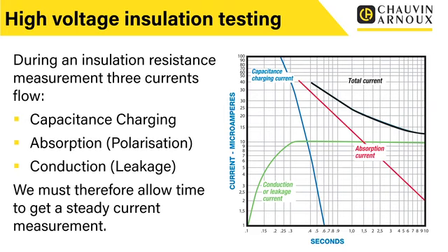Obviously using a DC test voltage, there will be a positive and a negative. Within that insulation, there will generally be a random alignment of all of these molecules within the equipment. When we actually place the insulation under test, there is a period of time where the insulation orientates itself and polarizes itself to that application of positive and negative.